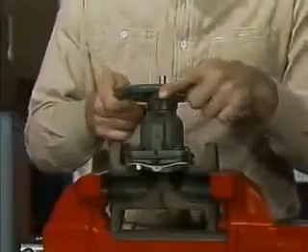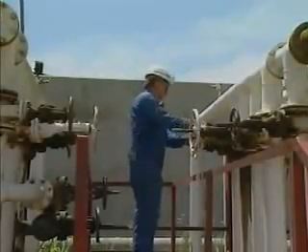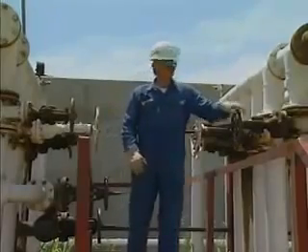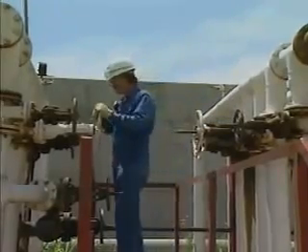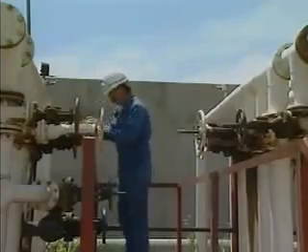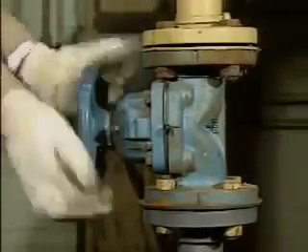When a hand wheel is used to operate a diaphragm valve, excessive force could cause the diaphragm to jam into the seat and be cut, resulting in leakage. Finally, to check if a manually operated valve is closed, try turning the hand wheel or handle in the proper direction to close the valve. This prevents undesired flow through the valve if it's already tightly closed. Many valves can be operated manually with hand wheels or with operating handles.